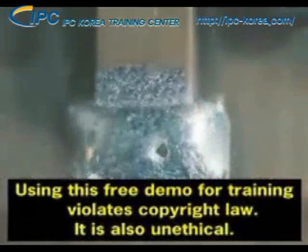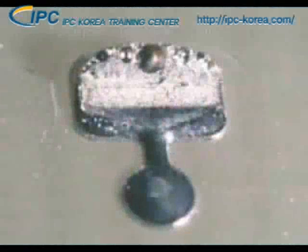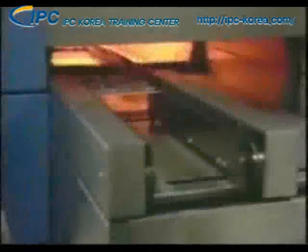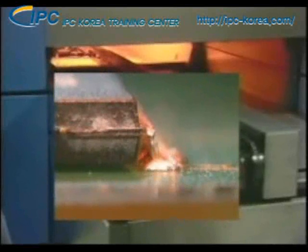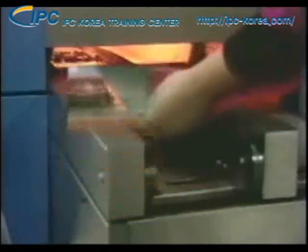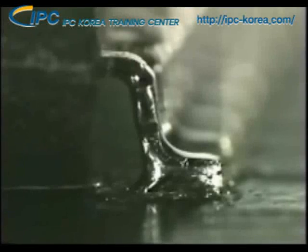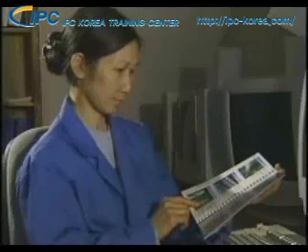Sometimes a solder joint will meet the minimum acceptance criteria, although it may exhibit certain cosmetic imperfections that are not detrimental to the reliability of the solder joint. These types of conditions fall into a category called process indicators. The idea here is that the process that created these cosmetic imperfections should be changed, rather than the cosmetic imperfection. This makes a lot of sense, because when you fix the process, the incidence of imperfections will be reduced or eliminated. Now let's examine the defect criteria for surface mount solder joints.